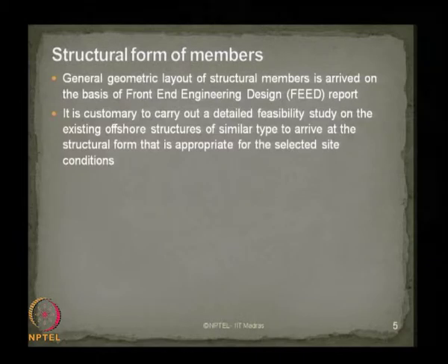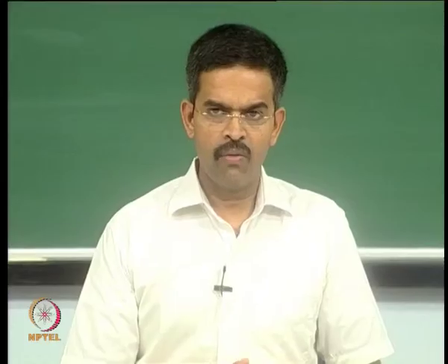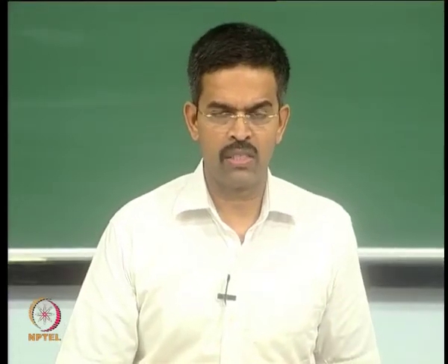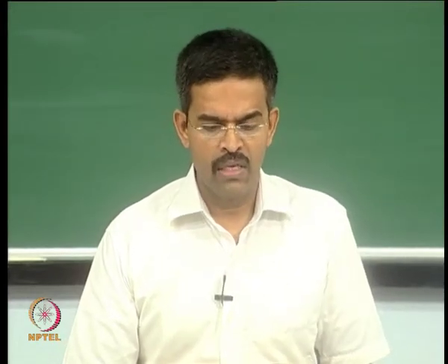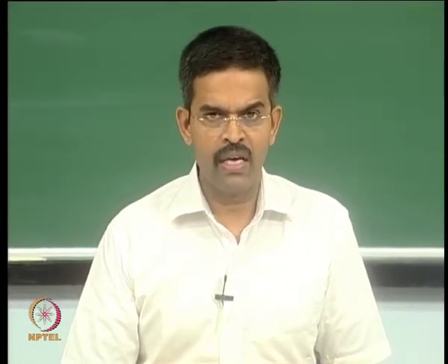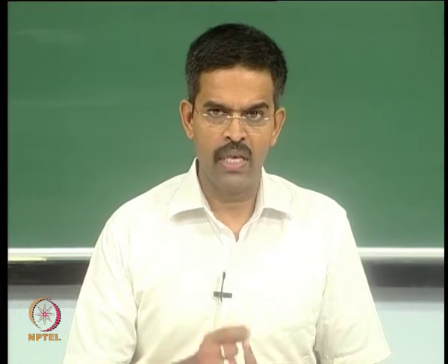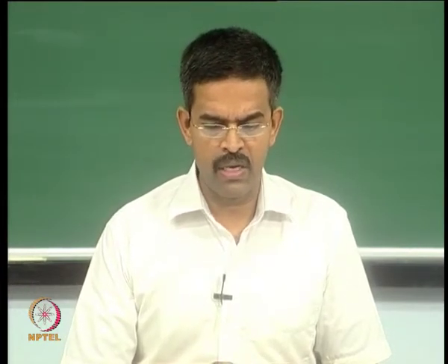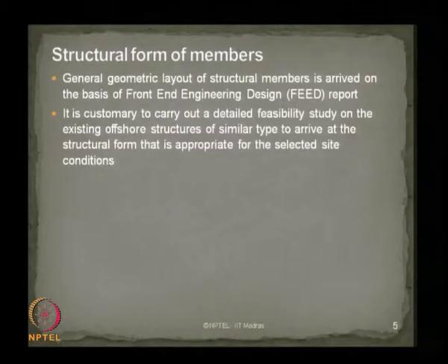It is always customary to carry out a detailed feasibility study on the existing structure of a similar type. For example, if we want to design a compliant offshore structure, it is always advisable that you conduct a detailed feasibility study on an existing compliant structure of a similar type to arrive at the basic structural form which will be appropriate for the selected site conditions.